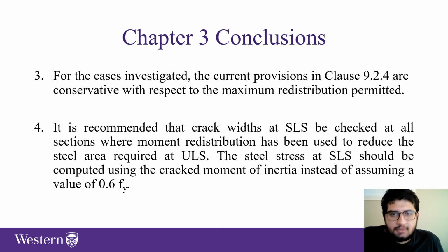The current provisions in clause 9.2.4 are conservative, and it's recommended that the crack width at serviceability be checked at all sections when the moment redistribution has been used to reduce the steel area that's required at ultimate limit state. The steel stress at serviceability should be computed using the cracked moment of inertia instead of assuming the serviceability stress approximation of 0.6 fy.